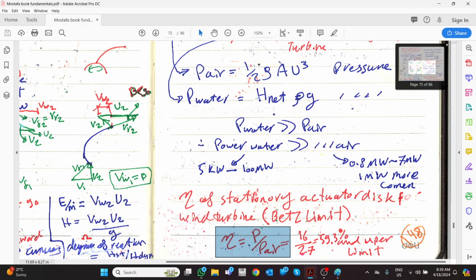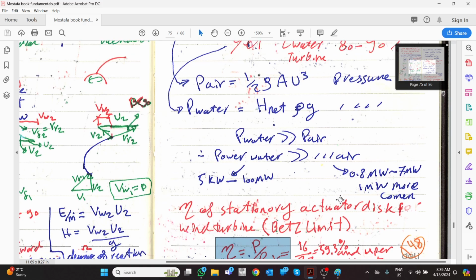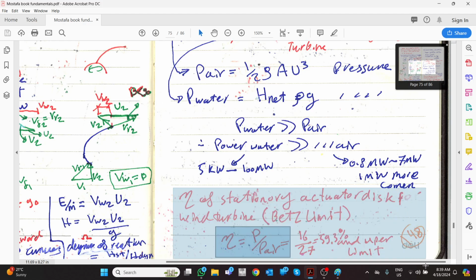and this percentage is the upper limit. So for any CFD model, whatever you do, if you find that your efficiency is, for example, 45 or 48 for the turbine, and you say the turbine is not efficient, take care, you will be a specialist who needs to know that no, this is really high efficiency. And of course, if you get more than this number, something is wrong with your calculation or your model. Okay, so we understand this part.